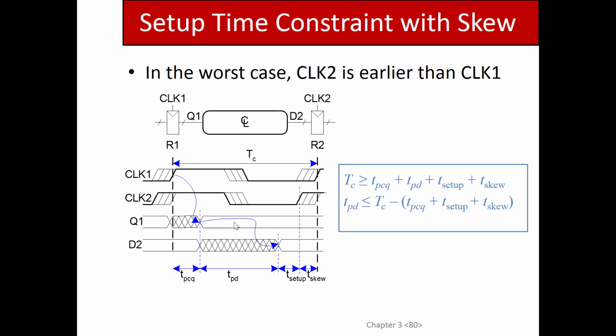So this is the same thing: we have the skew. Again, the skew is the worst, the highest possible difference between two clock edges on the same chip. That's the skew. Now, by the way, this is kind of a gamble you play. In fact, I do this all the time. I'll do a design on an FPGA, and you run the timing analysis, and the tools will say, oh, this design should run at 200 megahertz. And I'm always like, I'm going to run it at 225 and see if it works.